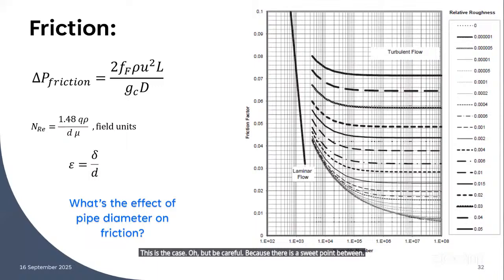The well loses all its productivity power when you increase the diameter too much, and if you decrease it too much, you will lose a lot of pressure due to friction. So you have to understand this, and this is very important to you. It will also change the fluid patterns in the well.